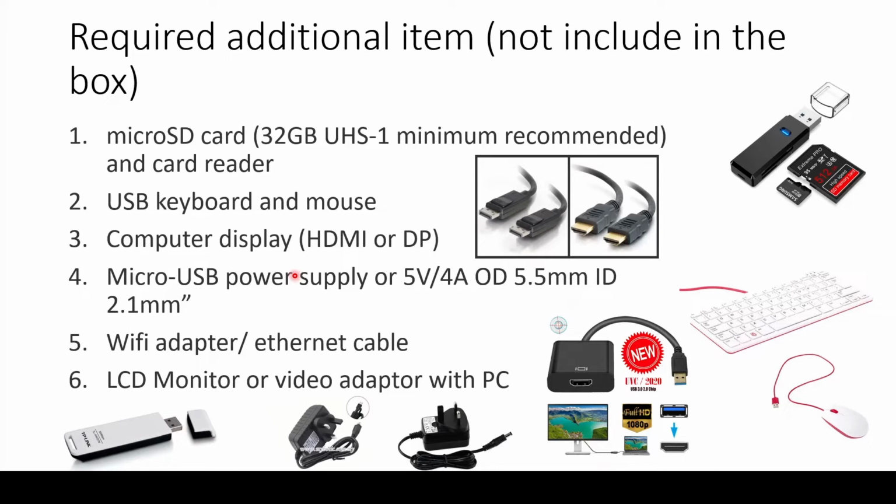And another thing is the size of the plug. Based on this, the end size here is 5.5 mm OD, 2.1 millimeter ID. Sometimes, even though the size is similar, the power rating is not the same, and it won't turn on the Jetson Nano device.